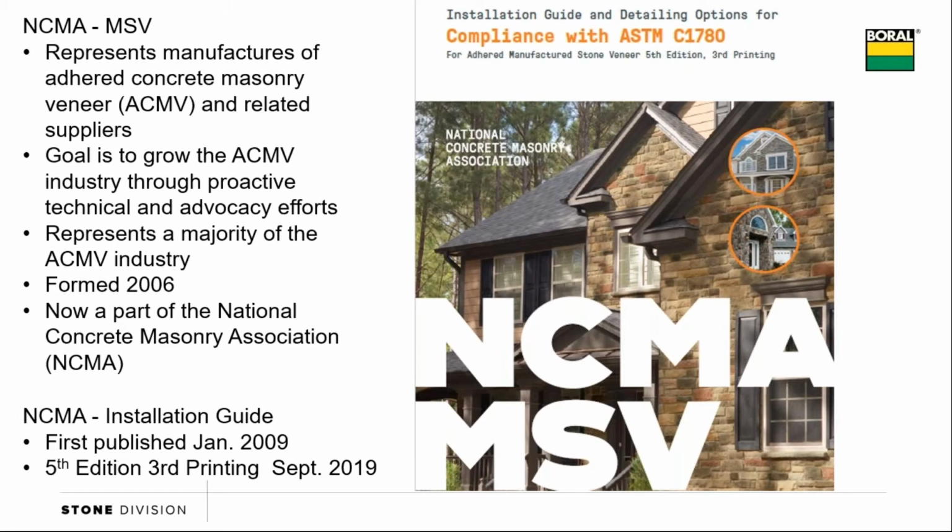If you don't have a copy of this, go ahead and jump on any one of our stone websites. In the installation part, there will be a link that will take you out to it, or you can go to ncma.org and hop into their manufactured stone section and find the guide. I would recommend downloading a copy and at least keeping it on your computer. If you're a contractor, keep a copy of it in your vehicle, in your truck. I can't tell you how many times I've gone to it as a resource. There's about 10 pages of phenomenal information around papers, laths, mortars, wall prep, and then about 40 or so details on flashings, transitions, and things like that.